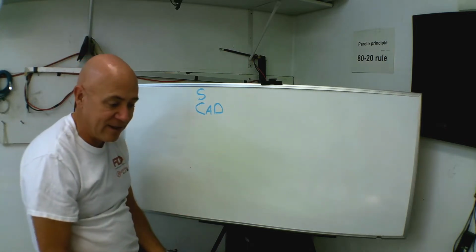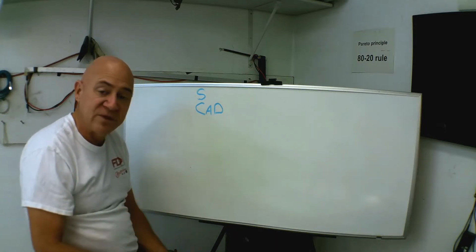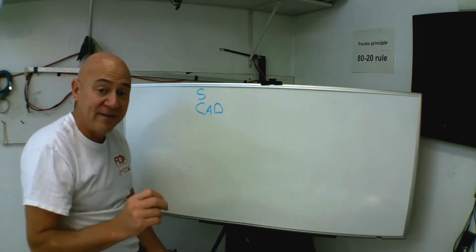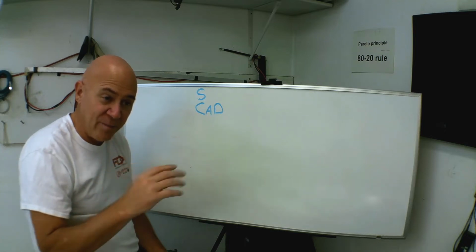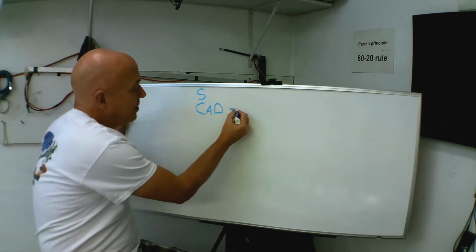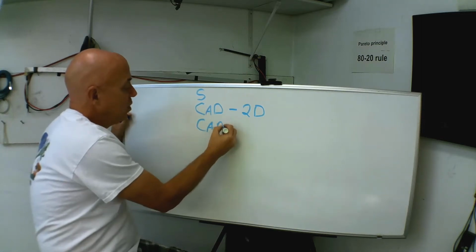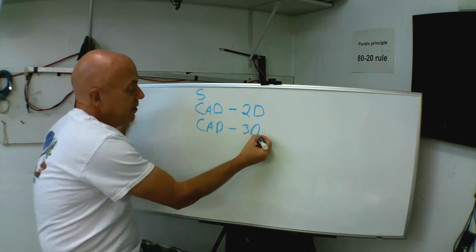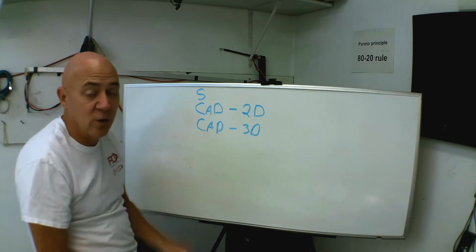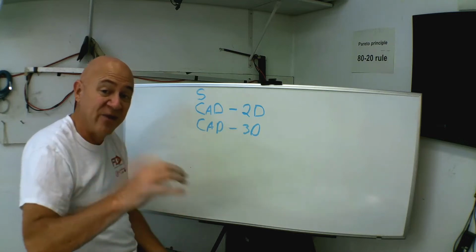And let's say the CAD is for printing out on my plotter some fuselage templates, wing templates, different parts of the fuselage. But also in CAD, I'm getting the dimensions and ideas of what I've got to do in other CAD programs. So this CAD program is 2D. This CAD program would be 3D, and it's basically for 3D printing things, okay? 3D is normally what I use. So I can export an STL, turn it into G code through a slicer, and 3D print something.